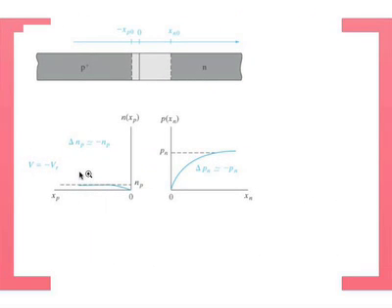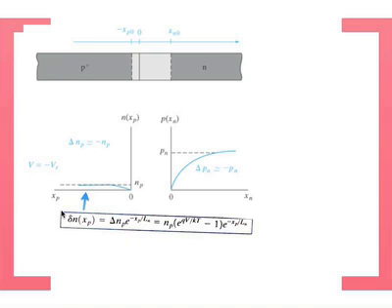Now, to look at this closely, we can calculate the excess carrier concentration with the same expression as before. Because it's decreasing towards the junction, you would expect diffusion to come towards the junction as opposed to away from the junction, right? So if you look at the electrons in the p-type material, they will diffuse towards the junction because the carrier concentration looks like that. And you can solve the diffusion equation again, and the expression basically becomes an exponential.